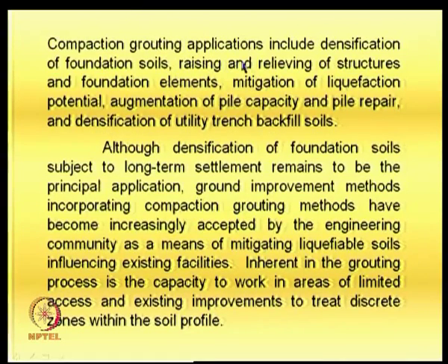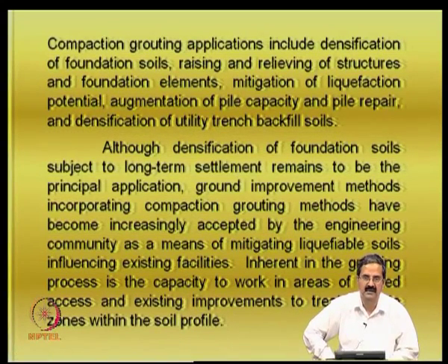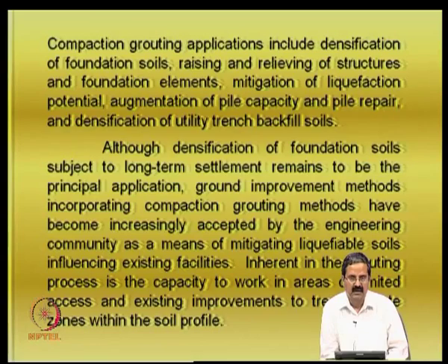So, the compaction grouting applications include densification of foundation soils, raising and relieving of structures and foundation elements, mitigation of liquefaction potential, augmentation of pile capacity and pile repair, and densification of utility trenches, backfills. So, for example, you know that the piles that you have designed may not have adequate strength or capacity, then how do you go about repairing it or improve the capacity of the piles. So, this is a very good remedial measure, a restoration measure, when there are no other ways of doing it.